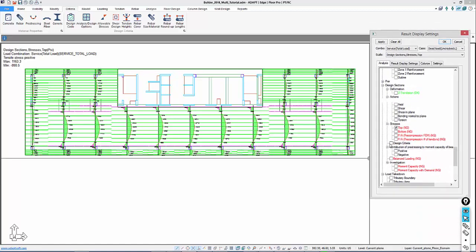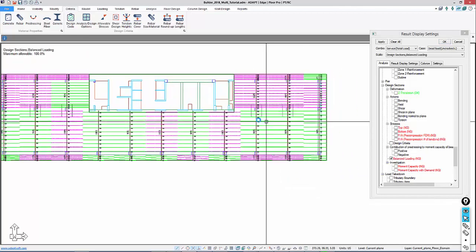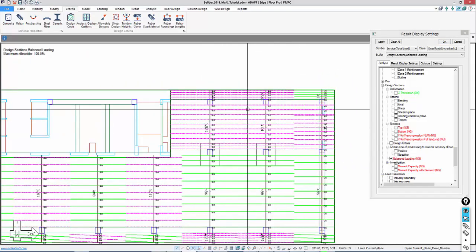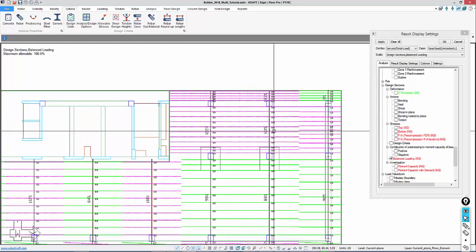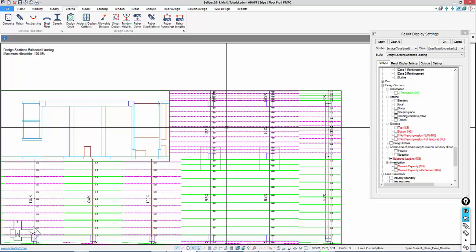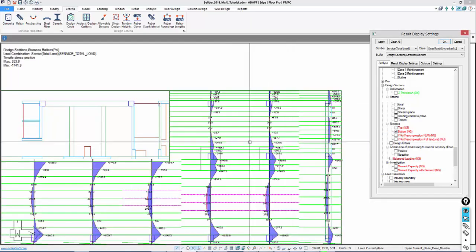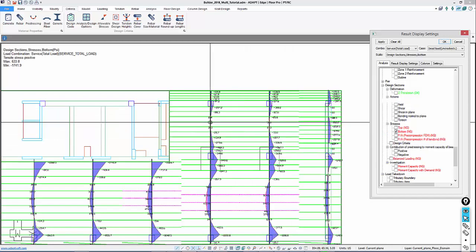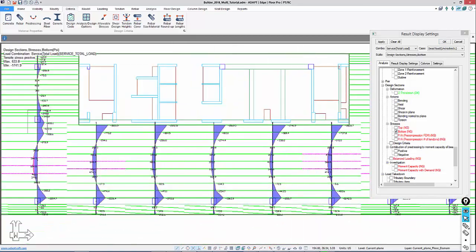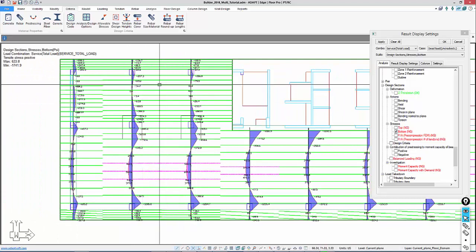Again, we might check balance loading in this direction. So we have, load balancing in this span here is high. We have the ability to drop the drape in the mid-span, meaning raise the profile from the bottom up. And if we look at the stress check here, again, we're kind of hovering near neutral, where we're just slightly in tension. So we have the ability to move that tendon up and not really cause a problem there from the stress standpoint. Same thing in this region here.